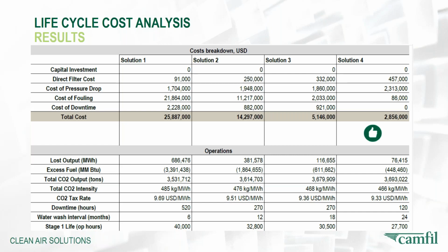We're also asking them to accept a higher penalty in pressure drop over that time frame. But we're doing that so that we can almost remove the effects of fouling from their system. We can't say we remove fouling; I don't think you can ever remove it all the way, but we greatly mitigated it, from a $21 million cost penalty for excessive fouling down to $86,000.